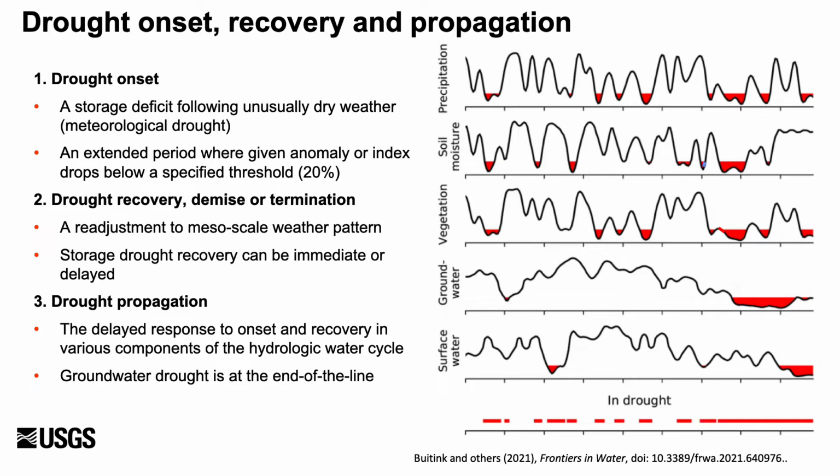More holistically, the rate of drought onset and recovery and its propagation through the hydrologic cycle can improve our ability to predict the response of groundwater and stream flow to these climate anomalies. Hydrological drought differs in dynamics from meteorological drought. The large size of most groundwater systems buffers the impact of meteorological drought, which is often delayed and attenuated with timescales ranging from months to years.